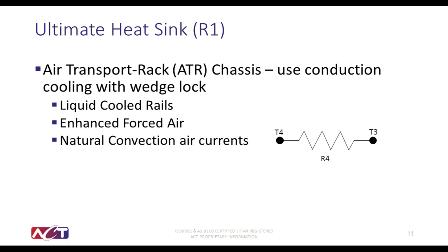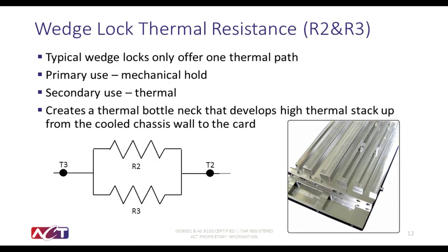Aluminum, with thermal conductivity of 167 watts per meter Kelvin, is commonly used due to its weight and strength benefits. However, with the low thermal conductivity, hotspots may occur, reducing the effectiveness of the surface area, or fin design.